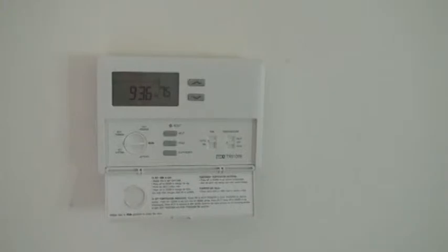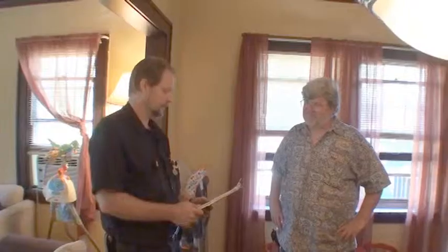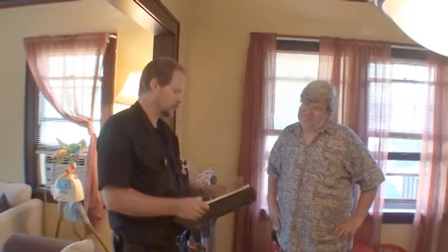When installing a setback thermostat, walk the client through the initial programming process and leave the owner's manual with the client or in the furnace manual pocket. Fill out Community Action's mechanical form and have the client sign Community Action's warranty form.